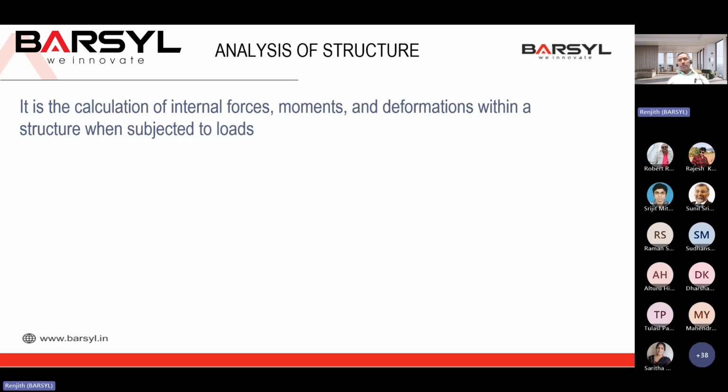In a cantilever retaining wall, earth is supported by the stem, and the stem bends in the other direction. So tension is at the earth face, and the major tension reinforcement comes at the earth face. The minor, or temperature, or minimum reinforcement will be provided on the other face, along with the distribution reinforcement.